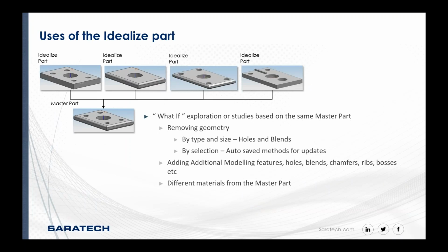So right here's a nice little picture. Maybe we want to remove those rounds. Maybe we want to remove some of those holes. Maybe we want to try and expand the hole. See, does this make a difference? Remove holes. Maybe we want to stiffen the plate or something like that. We can make these changes to the idealized part, and we aren't editing that master part.